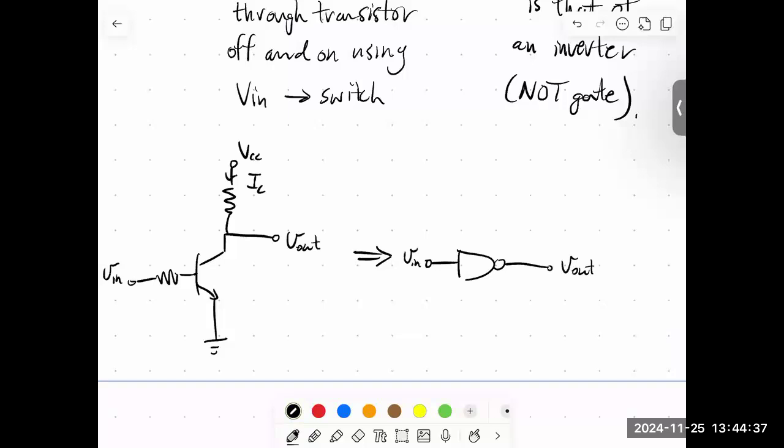Okay, good. How much time do we have? We have 6 minutes. Let's do one other thing. We've only made one of our logic gates. We've made the NOT gate. Notice that it's a 2-terminal device. It has a 3rd terminal, but that's like the power terminal. So remember, the inverter chip to be used properly needs to be powered, and it needs to have a ground connection. In the chips that we use, the power was going to, like, I don't know, pin 14 or something, and the ground was pin 7. So those are those connections, and then we have an input and output left over, and so that corresponds to this.